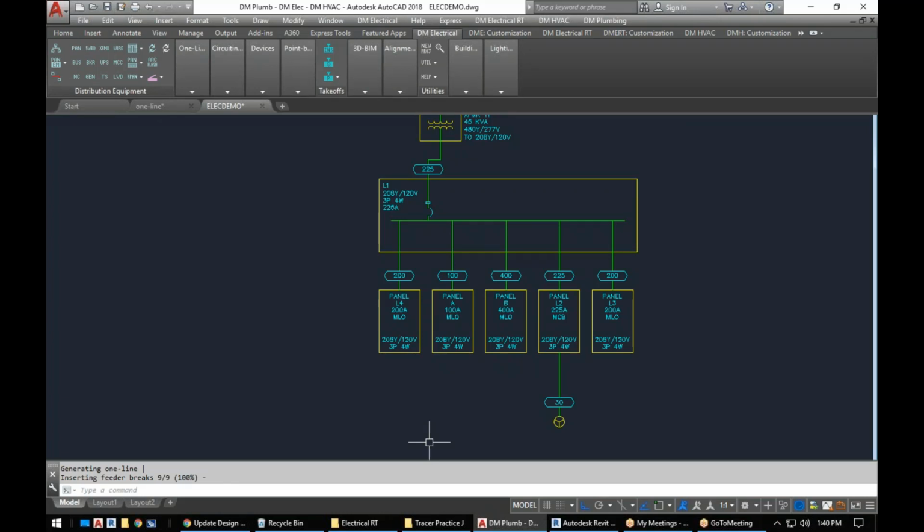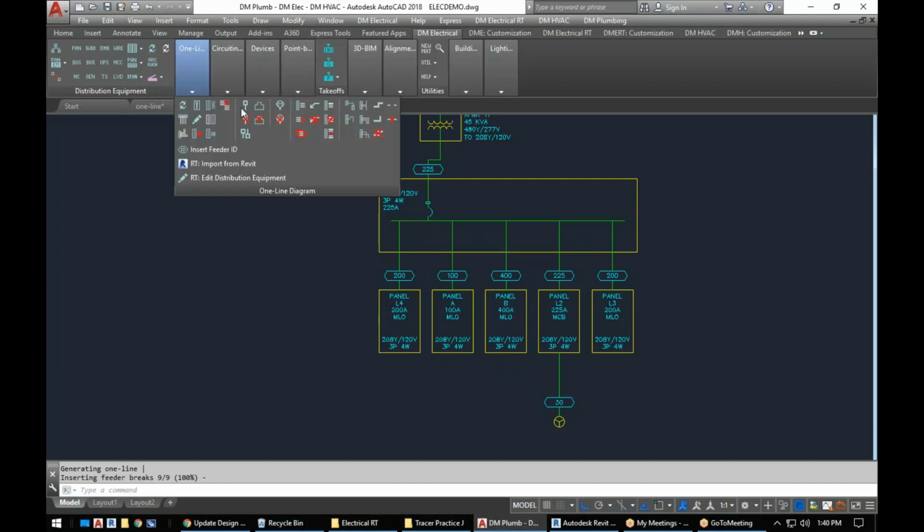It's not actually what we would ever recommend for a standard workflow. If you're having to erase and run the generate command frequently during the course of a project, something is wrong. So please don't do that. You should really only be doing this when you're trying to get your standards set up. But when you're working on a standard project and all the standards are right, you shouldn't be running the generate except to add a couple additional things. If you're erasing and regenerating, that's actually bad. So you should make some adjustments to your workflow so you don't have to do that, because the software is not going to work well if you do that.